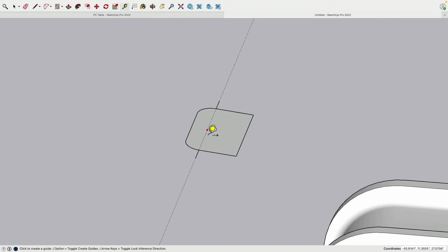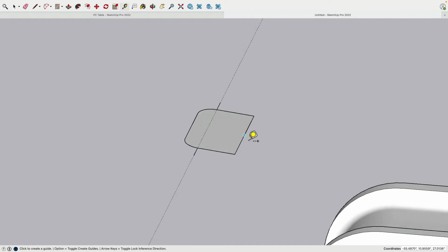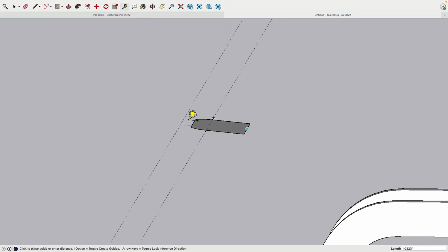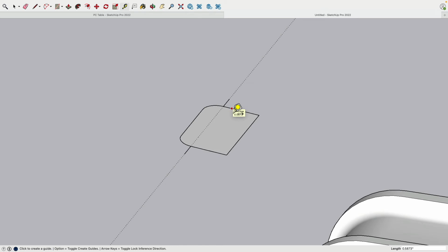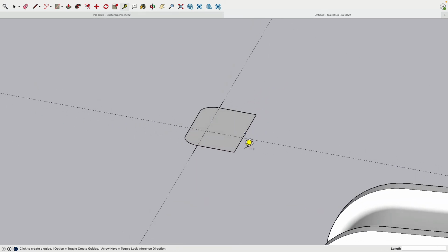How do we get this done? Again, because we have a face here, it's really easy. I can now, yeah, I think so. On this face, I can bring a line, but then the moment it's off the face, it's horizontal again. I need a ray to help me, and here it is. I'm just making this guideline on this face, and then I make a guideline along this line.